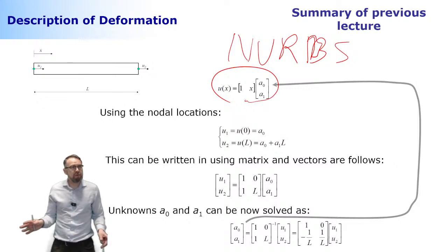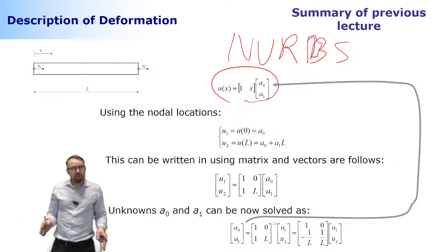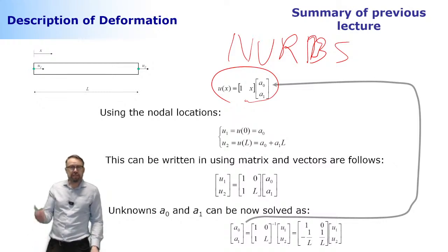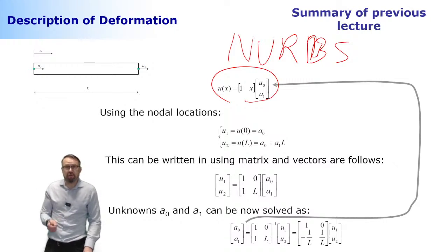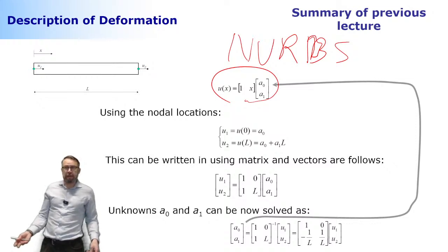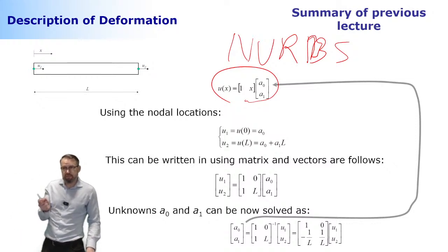And it's a kind of simple thing. You're selecting the order of the polynomial expansion based on the number of degrees of freedom. That's basically what you need to do. And you can select these polynomial components in order, or you can skip some of them. If you skip some of them, you get non-conformal elements that may or may not perform better than the ones that are selected in a row.